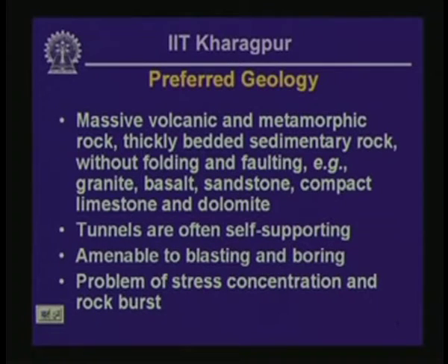So, it is going to attract quite a large concentration of stress, particularly near the corners of an underground excavation, and such concentration of stress could in fact become so large that under that amount of stress the rock mass is going to fail in an often explosive manner, because strong rocks are often brittle. So, they are going to fail in an explosive manner, and what it is going to end up in is a phenomenon called rock burst. Okay.